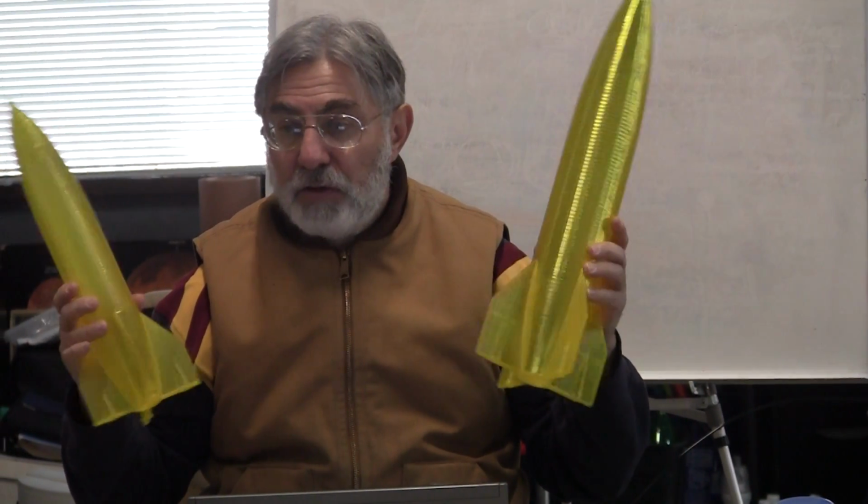This was made with a different extruder, with a 1 millimeter nozzle and a layer height of about 0.6, 0.7 millimeters, and this took maybe about 3 hours. Now, if you look at it, this is thicker and stronger, but you can really see the layers. You can still see the layers here, but they're much finer. So, as with everything in engineering, there are trade-offs.